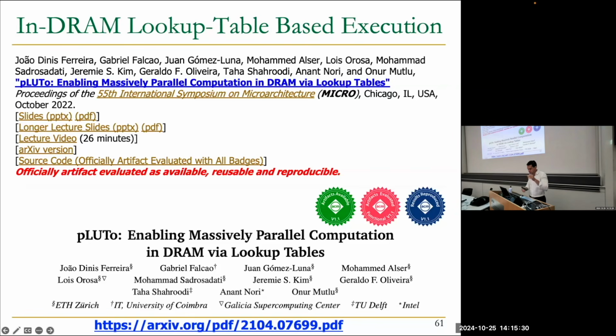Okay. So where were we? We were doing processing-in-DRAM operations, right? So now we can do in-DRAM row copy. We can do in-DRAM majority operations using Ambit, and we can do arithmetic operations using SIMDRAM. So if I want to make this a compute engine, can you tell me what type of operation I'm missing?